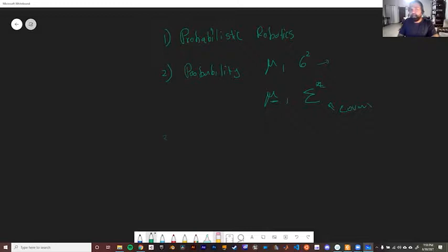And then we learned a simple example of the Kalman filter. I want you all to remember it has two steps. It does a prediction, and then it does what we call an update step. In the prediction, it uses the motion, the control signal, to predict where it's going to move forward, including the noise that is there in the control signal. In the update, it takes the observations from the sensor information and updates this control-based prediction to get a better answer.